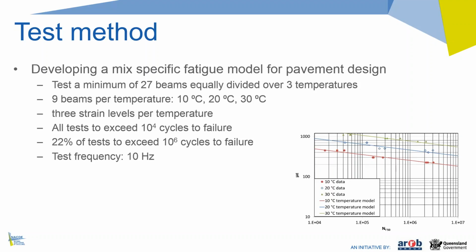I'm just wondering, Eric, those 27 beams, I understand we have 5 beams for the modulus testing. Can those same beams be used for the fatigue testing, or is this another 27 beams? Yes, there's nothing in the test method to stop you from using those same 5 beams. I wouldn't necessarily encourage you doing that, because I would be worried that you have imparted some damage on those specimens through the modulus test. But the test method actually allows you to do that, because it's based on the European test, which also allows you to do that.